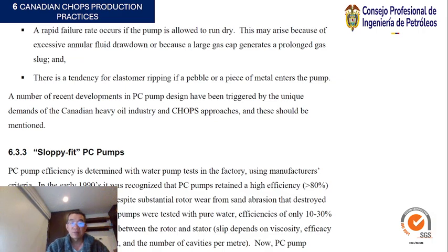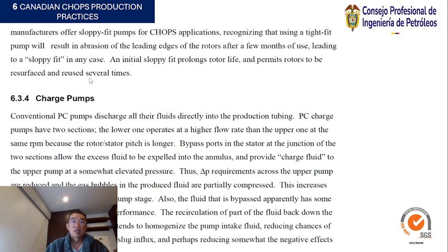Now, PC pump manufacturers often supply sloppy fit pumps for CHOPS applications, recognizing that using a tight fit pump will result in abrasion of the leading edge of the rotors after a few months of use, leading to a sloppy fit in any case.